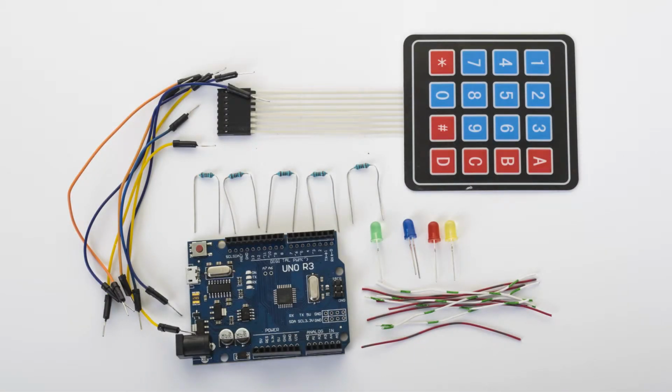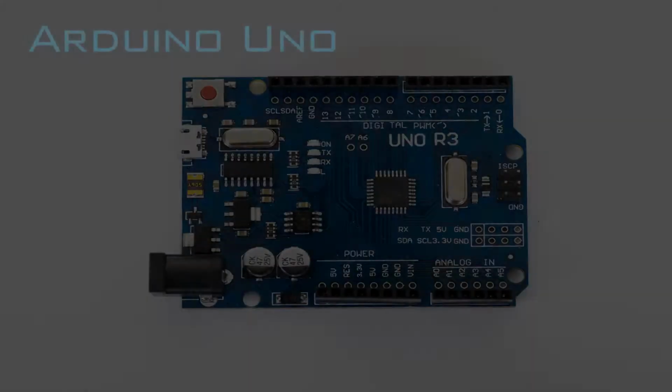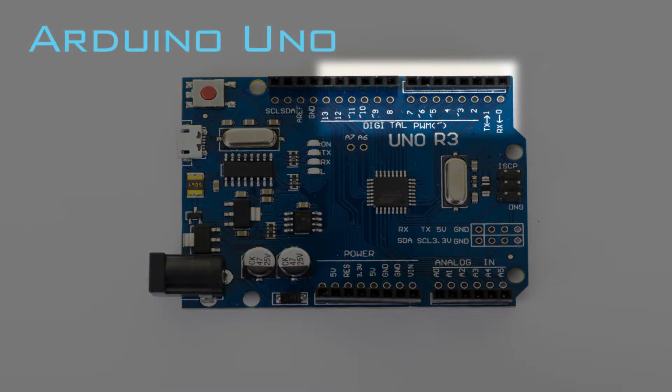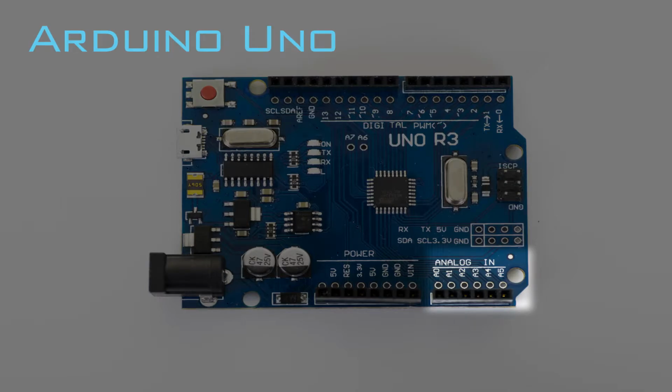The project consists of several components put together to form one working digital organism. The central, most important unit is the Arduino board, which is responsible for a number of functions, from processing the code, outputting the signal, and storing the data to the internal memory. All of the other components are connected to the Arduino board via a series of pins, either digital, 1 to 13, or analog, A0 to A5.